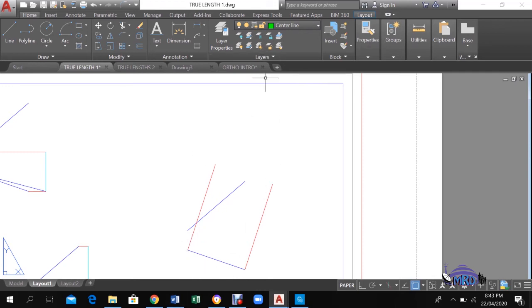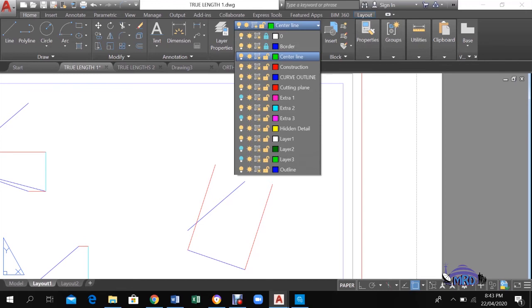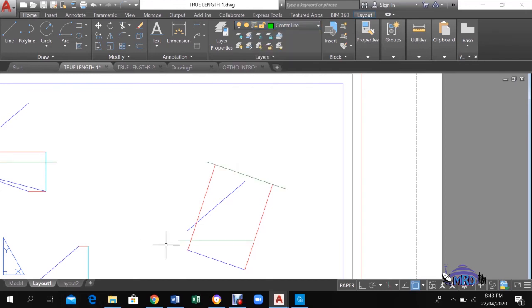Now, I will now show you the XY lines in position, because this would have been your original XY line. So once you've pulled those 90-degree lines, you also now want to put in another XY line. This XY line will be parallel to the line that is represented in your plan. Remember what you would have done on true shapes.